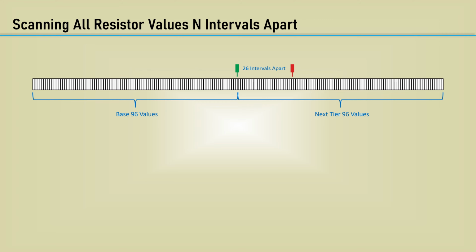We will not use a loop of 192 values. We will just simply wrap the upper pointer 96 steps back. If the best fit value is in that region, the top resistor value will get scaled to 10 times the value of the one in that pointer.